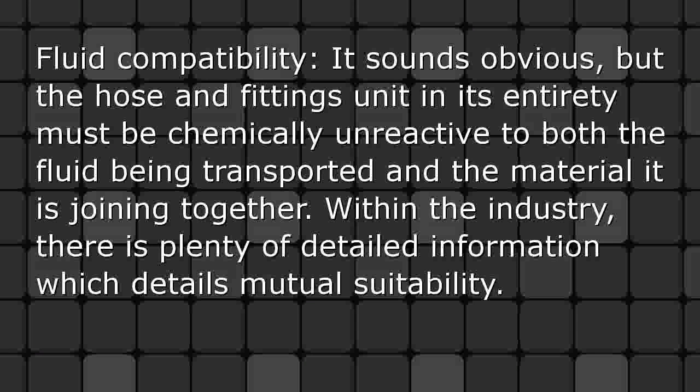Fluid compatibility. It sounds obvious, but the hose and fittings unit in its entirety must be chemically unreactive to both the fluid being transported and the material it is joining together. Within the industry, there is plenty of detailed information which details mutual suitability.